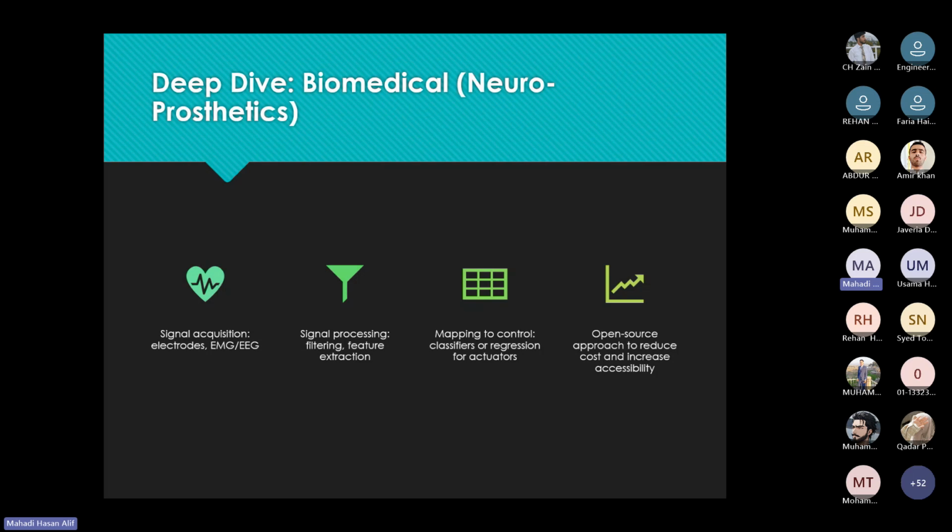We don't want those. So after we have the exact signal we want, we'll do a mapping to the exact things that is an actionable outcome. For example, we are taking a signal from the brain, and at this stage, we will write the code for how that signal will get mapped to a movement on the robotic arm that we have developed. So at this step, we are analyzing generally a lot of data, a lot of signal, and using the previous statistical analysis, we're mapping each signal to each actionable outcome.